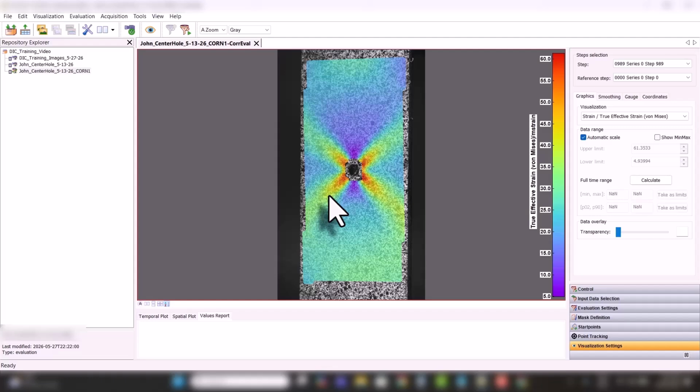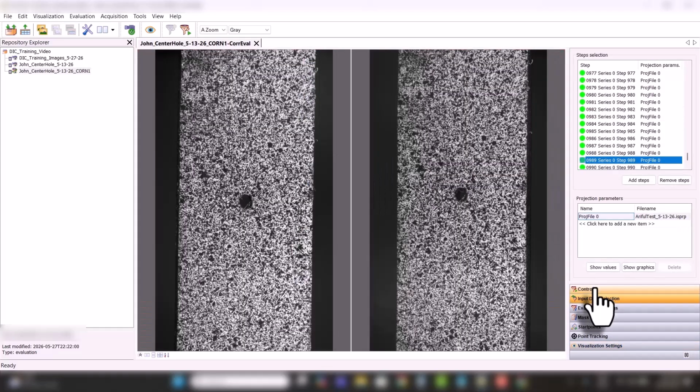In general, it's going to be larger facet sizes. And here, since we're not dealing with a crack tip or a notch edge, we can make the facet sizes large, and it's not an issue. We don't have to compromise here trying to hug up next to an edge. So that's nice. We can make the facet sizes larger and then just put rung steps at different spots. Look for images where it seems like there's been a significant change, or where the correlation starts to really fail.